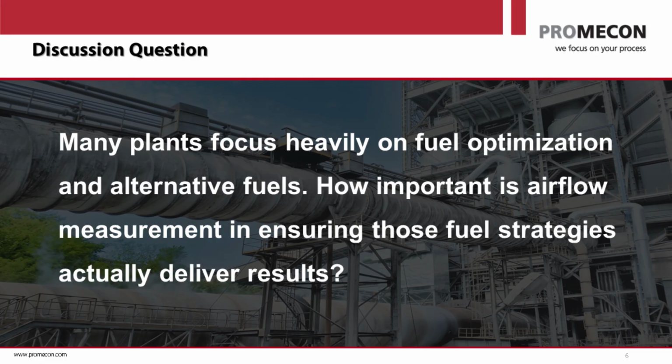So the highly dynamic flow signal, because it's refreshed every second, takes care of the short-term process variable to stabilize the ID fan. And the O2 analyzer, which is much slower in its response, provides longer-term adjustment. And thus, you eliminate systemic process noise and you avoid a potential slipping of the pyroprocessing into a transient state.